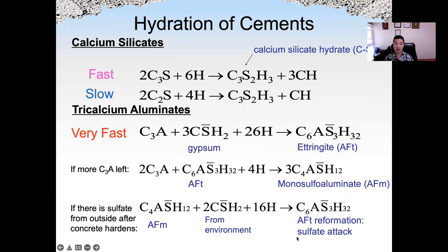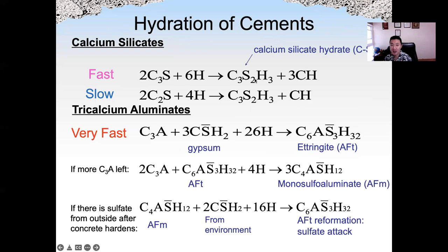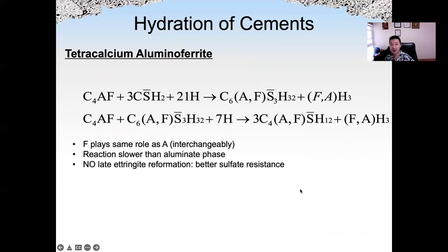And this chemical reaction we call the hydration of cement, for C3S, C2S, and C3A, which is more complicated, and also C4AF. And we know we have CSH, calcium hydroxide, ettringite or AFT, and monosulfoaluminate as the major hydration products.